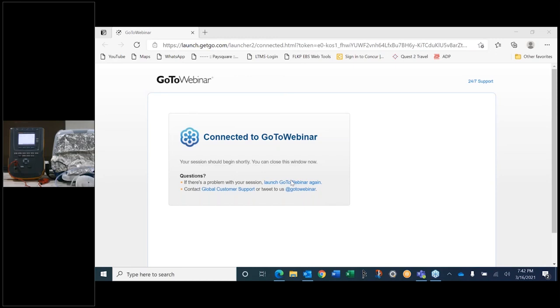Yeah. To add to that, actually the manufacturer will specify at what DC voltage, I mean to say, whether you need to do it at 250 volts or 500 volts. Equipment will have the built-in capability of testing either 250 volt DC or 500 volt DC. See, you can change it to 250 volts or you can do it at 500 volts. I will do it on 500 volts testing.